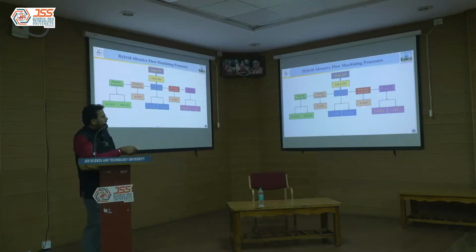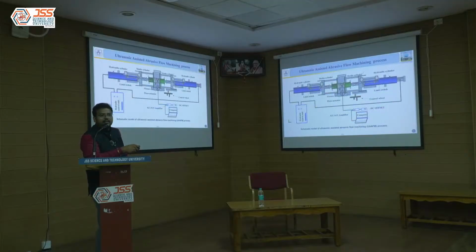That is ultrasonic assisted abrasive flow machining and rotary based abrasive flow machining. Our project is actually combining these two. First let us discuss ultrasonic based abrasive flow machining. We have a case study on this, and then we will see the ML algorithms and their approach. Here the setup looks horizontal. The setup we developed at NIT Warangal is vertical. This setup was developed at IIT Roorkee when I was working there.